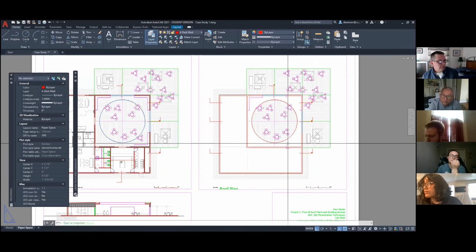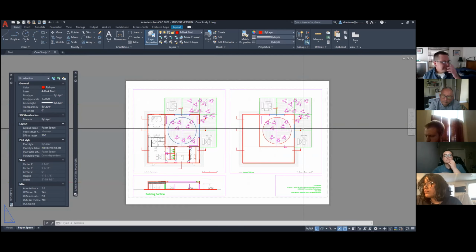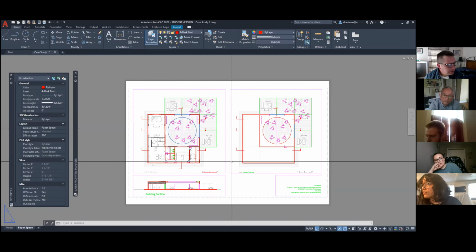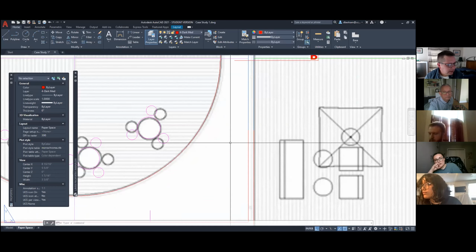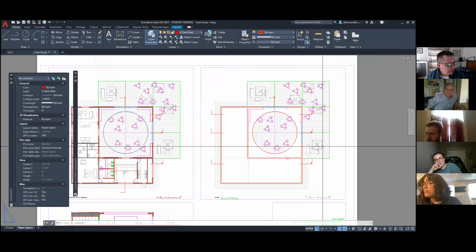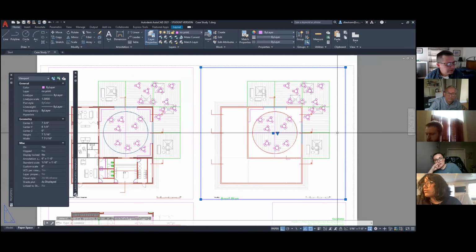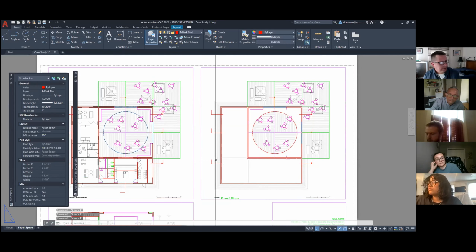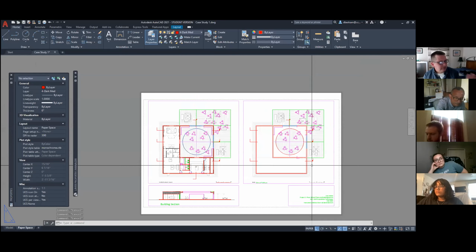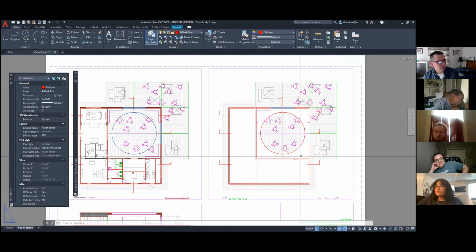when you're looking at this piece of paper, there's no reason ever to really zoom in like this. That's really when it all goes wrong. You should always be able to see your viewports, I would say. I can't think why you wouldn't see them. In model space, you really zoom in a ton. But here, it's better if you could see your piece of paper, see your viewports.